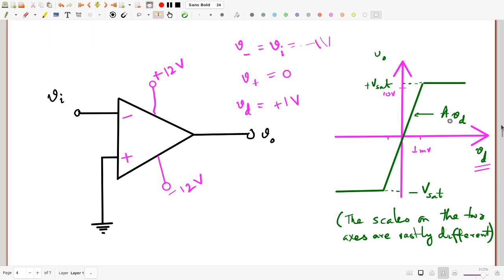So what this circuit does is something quite non-trivial. It compares the input voltage with 0 volts, the voltage which is being given to the non-inverting end by grounding it, and if the input voltage is more than 0 volts, you get a negative output, minus Vsat. If it's less, you are going to get plus Vsat.